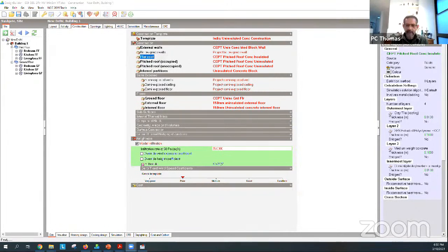Yes, there is. If you read the DesignBuilder documentation, there's a way for you to set up a new location. So with that location, you can bring in your own EPW file and it will do the calcs. It's all there in the help file. Go and have a try. If you can't make it, maybe we can help you out, but it's all pretty easy. You just have to give it a couple of tries to get it across the line.